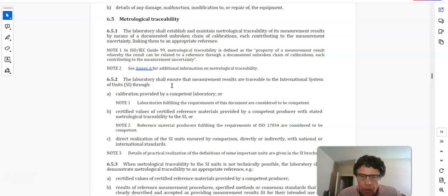You now have one year's worth of data that is suspect if you're using a balance and that balance impacts your test results. Because you don't know if that balance went out of calibration on 5/2 of 2024 or 4/30 of 2025. You don't know.